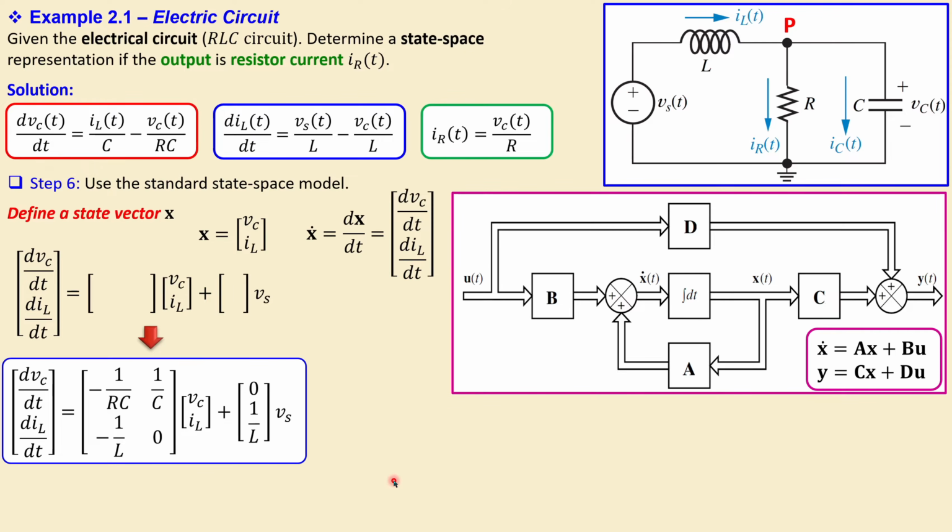You can say, okay, how is that happening? Now let's check that, because the first time derivative of that capacitor voltage is equal to, as shown here, 1 over C times that inductor current minus 1 over RC times the capacitor voltage. Now if the capacitor voltage is up and the IL is down, in this format, we know from linear algebra for multiplication of matrices using vectors, this must be multiplied by the first element, and this one must be multiplied by the second element of our vector.